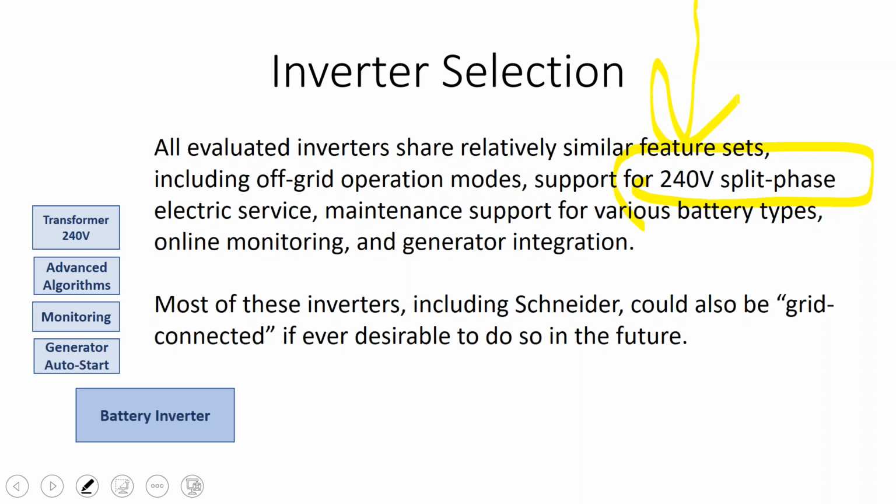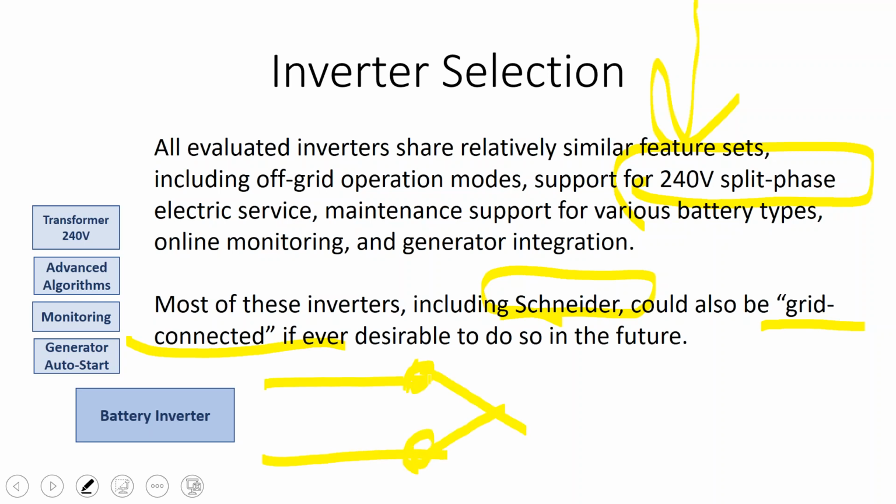One thing that we were looking at with Schneider is that Schneider had two. It's rated for doing off-grid and grid connected. And so on its inputs, it has two inputs, one from a generator and one from the grid itself, before you land onto the inverter. And we're using the generator, but we're off-grid. So we don't need to go with the more expensive Schneider inverter that has two AC inputs. We could go with a cheaper Magnum inverter that only has one AC input.